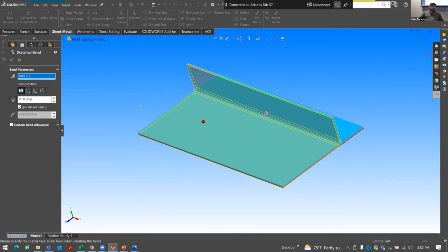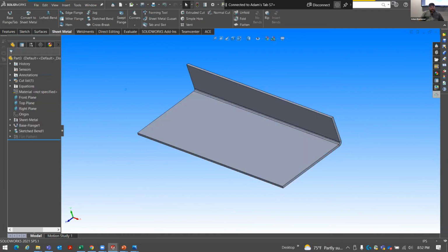I told it what surface I wanted to lay down and then pick the other surface up. So almost like I'm sticking it in the press brake, right? I want the surface to stay down, and the press brake's bending the back surface up for me. Basically, that's the way you could think of it if I'm holding it in my hands. It does serve a purpose. I guess if you're in a top-down assembly and you've got a piece of sheet metal you're sticking in there and you're trying to line something up, you could work it that way. But I use a lot of other tools that are a lot quicker than that.